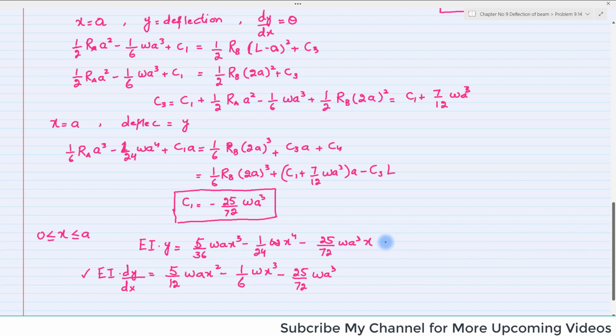Clear? Now, if you divide both sides of this equation by EI, you will get the equation of the elastic curve that can be used for finding the deflection. And if you divide the slope equation on both sides by EI, you will get the equation of slope for x greater than or equal to 0 and less than or equal to a. Clear?